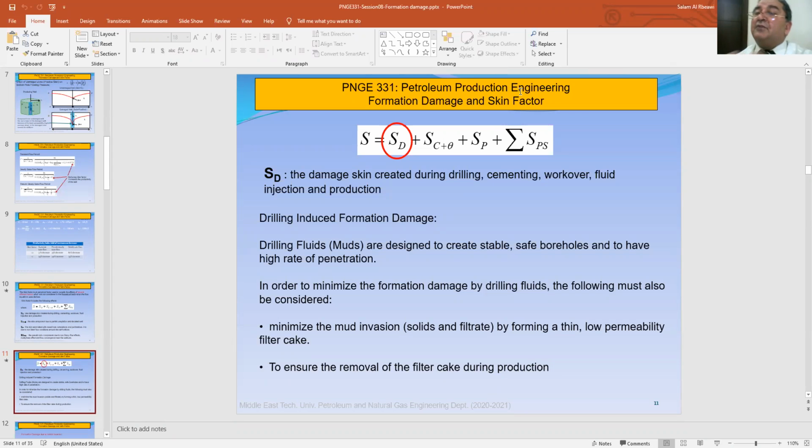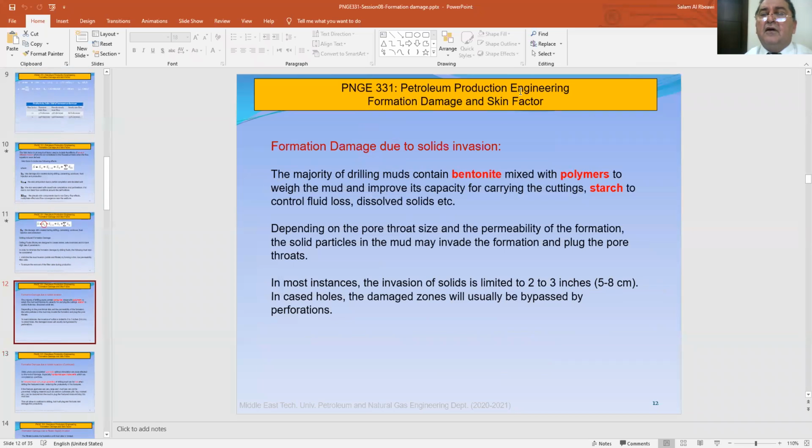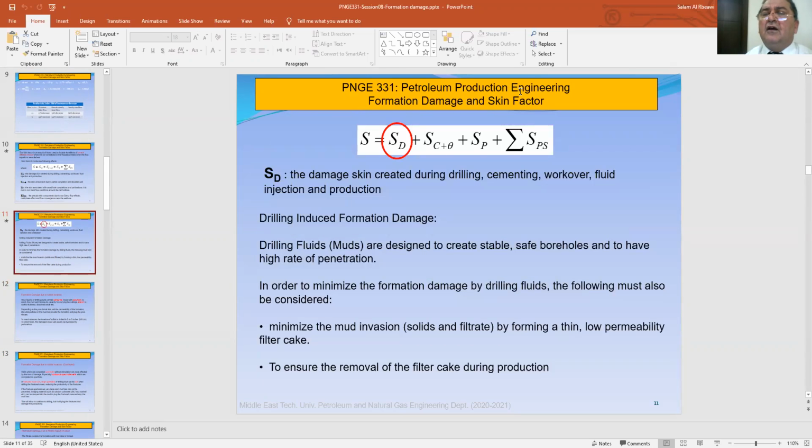The drilling mud is prepared from water plus the bentonite, barite, some of the polymers to increase the viscosity and enhance the cutting capacity of the drill cuttings, and some other chemical additives like gum and starch to decrease the fluid loss or the loss of circulation.